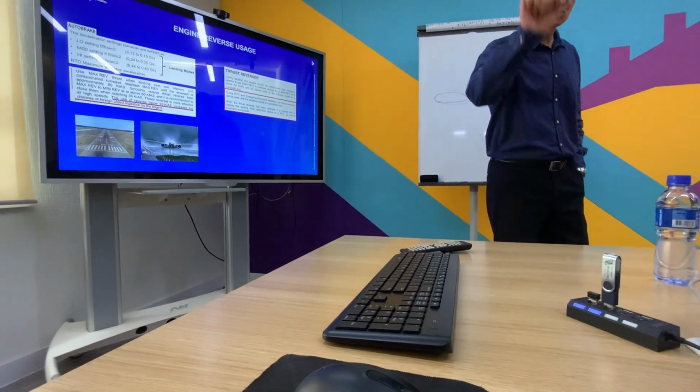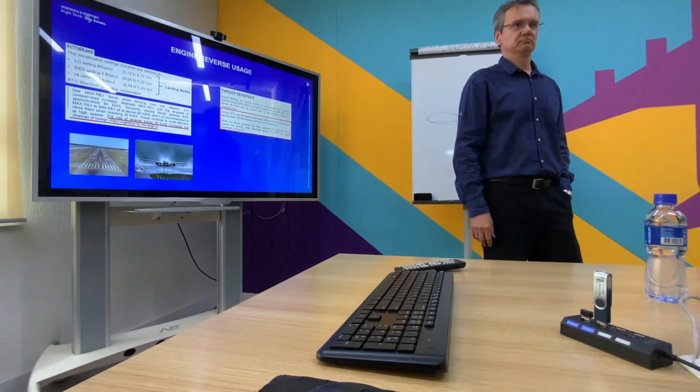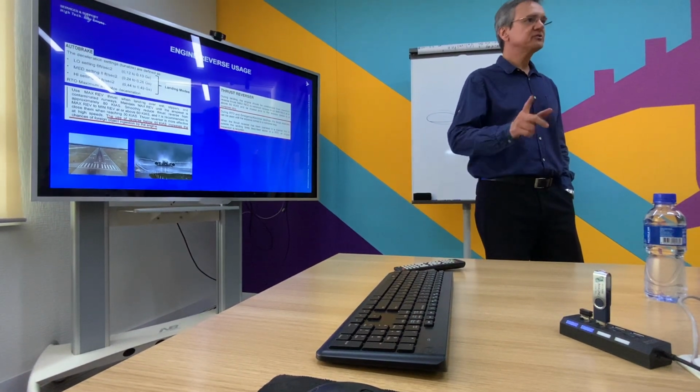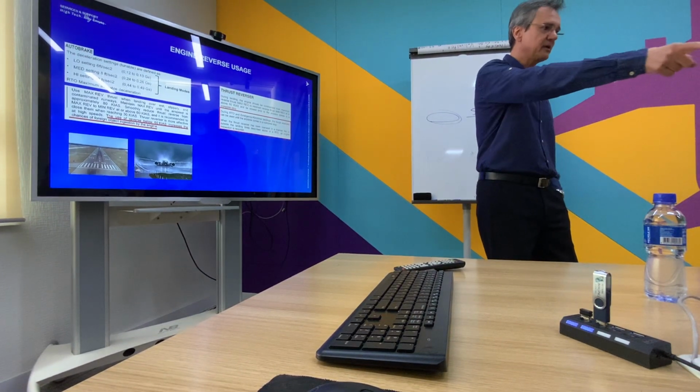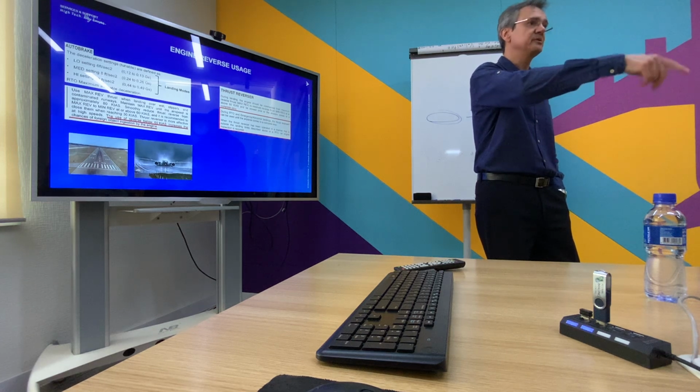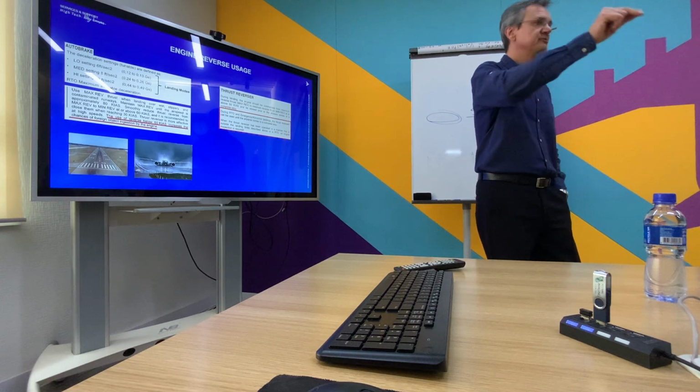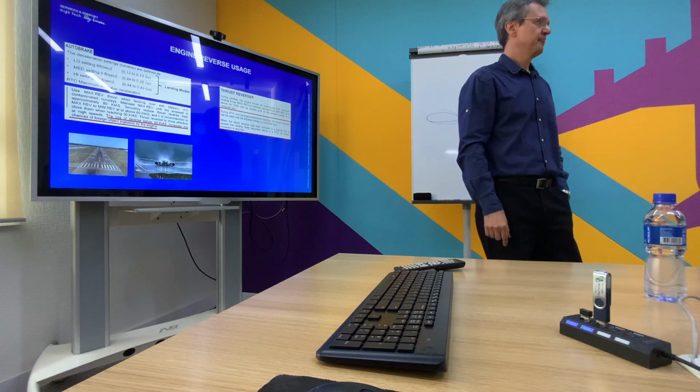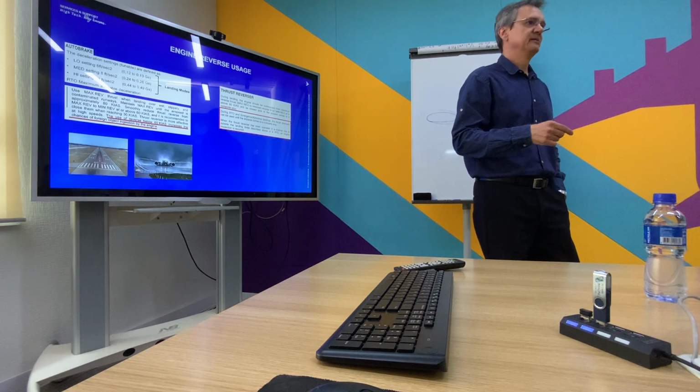Not in idle, stow the reverse. 60 knots. That's why we set on the ePerf, on the SOP, 60 knots for reject takeoff and for landing as well. Nowadays it was an update on the SOP, on the Embraer SOP.